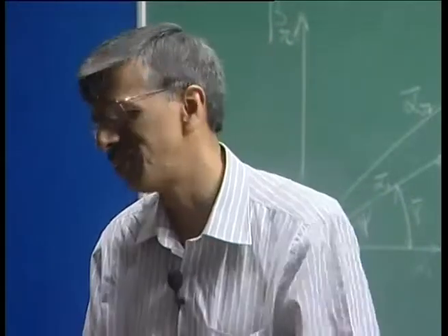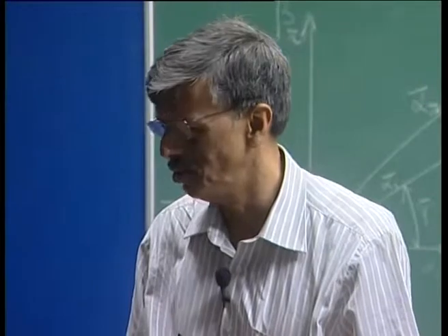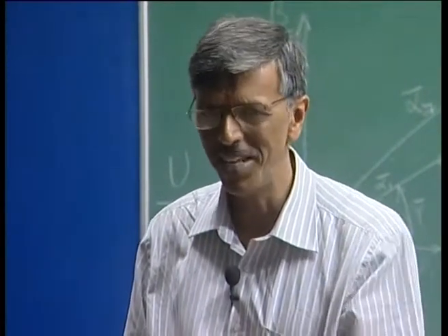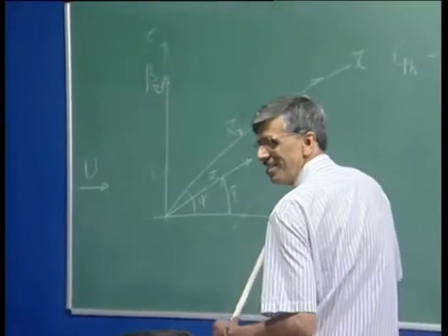You will see all kinds of disturbance, and the better thing to do is set up an experiment. You put some kind of exciter on the wing, a point exciter, let us say a mechanical vibrator on the wing, and vibrate it, and from that single point disturbances will come out in 3 dimensions, and there you will see all these nice things.